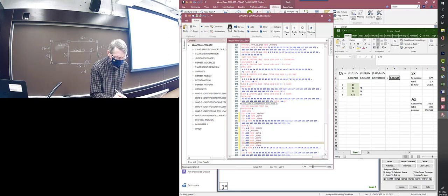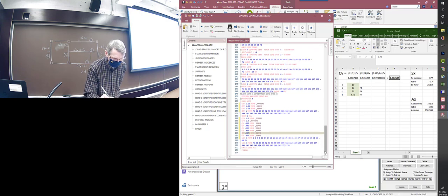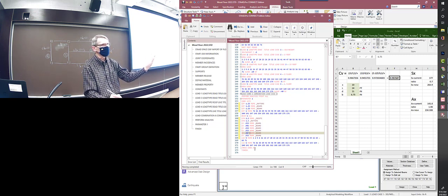This was the bracing, 5 foot on. This must be rafters and beams. Okay, I think I'll just leave those. And then we do the code check on everything. So that you've got all those parameters set that you need to set, and then we do the code check. And the code check's the last thing, and then that'll tell us again who passes and fails.